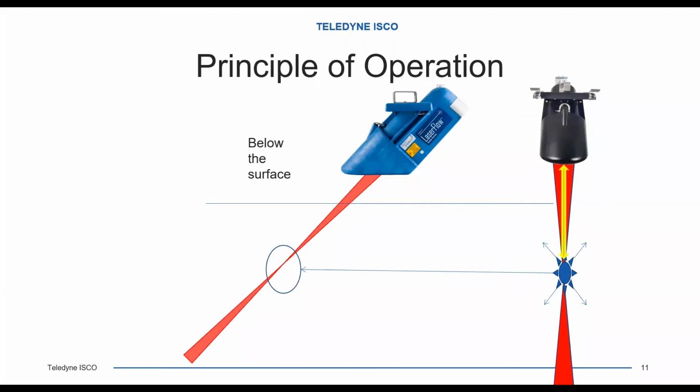Where it hits that water, you should see a very, very tight laser point. If you do, then all is well, and it's going to probably read. If you don't see a very tight point, then something isn't right. It either doesn't know where the water is, or maybe there's a program error. This is what we call the converging section or point of convergence. What's pretty interesting, or unique, about laser is that it takes 5,000 velocity readings, and it does all of that in 2 seconds. By comparison, a regular area velocity takes 512. Laser takes 5,000, and it does it in a very, very short amount of time.